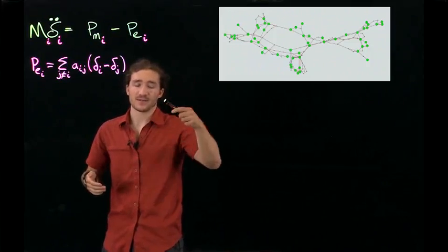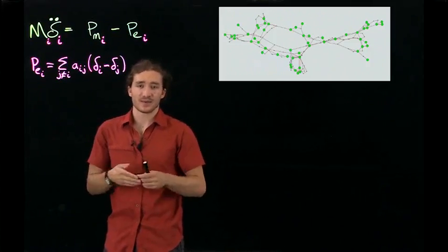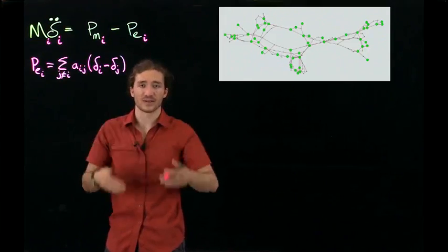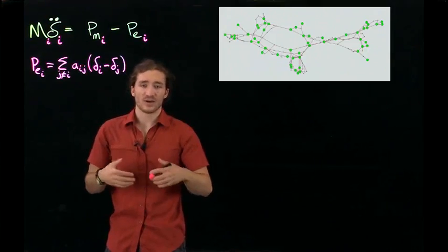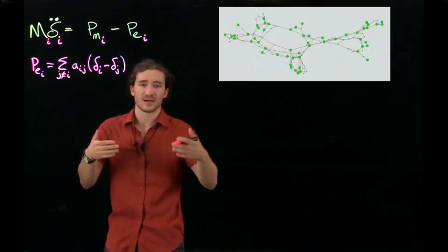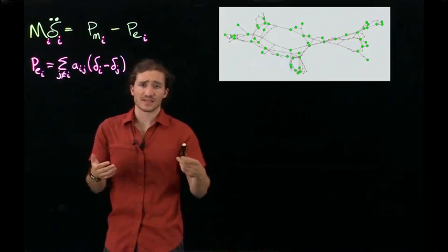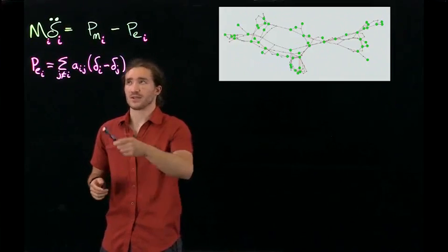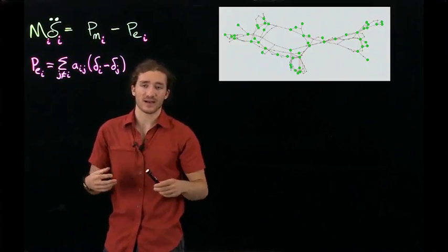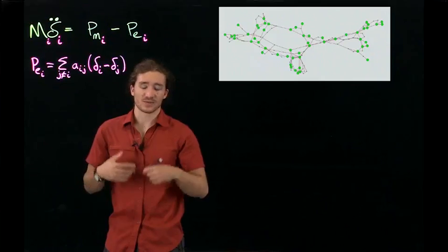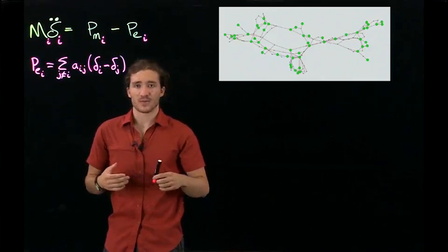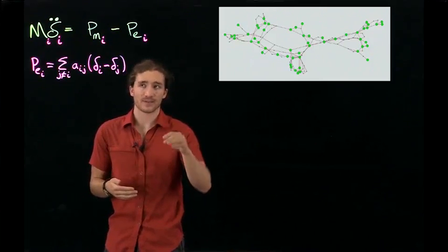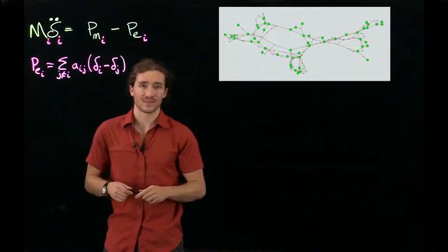And so it might speed up to the point where it's leading more than it was lagging. So we can have this oscillation where the oscillation is actually growing instead of decaying. And we call this the network destabilizing. And this is bad because when generator I starts accelerating quite a bit, there's large momentums on generator I, which will stress the generator. And so before the generator starts becoming damaged, power engineers will take it offline.